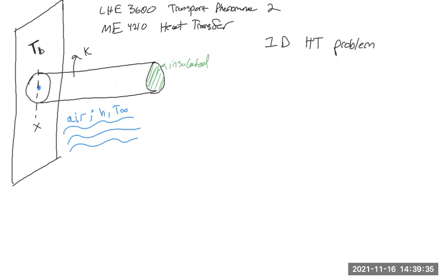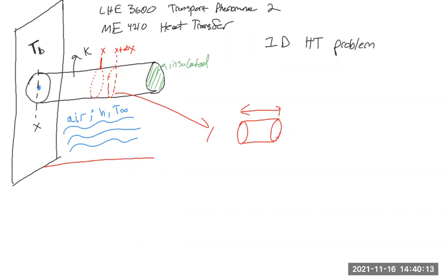Okay, so let's look at an arbitrary section of this cylinder, and we'll zoom into a differential control volume there. Let's say I want to look at this cylinder here. This is at some location X down the cylinder, and here I'll draw another cross section at location X plus delta X. If I zoom this out over here, it's the same cylinder, except the length here is different. Usually you'll be told the fin has some length L. If it's a cylinder, we know the radius or the diameter. Here, this is at location X, and this is at location X plus delta X.